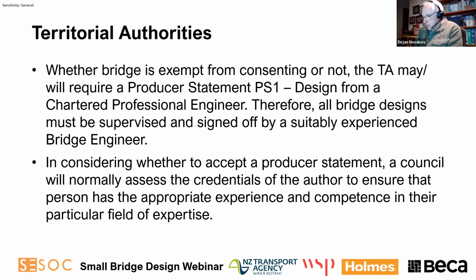Without repeating most of what was discussed previously, I might just add a few more things and refresh again here. First, to start with TAs and consenting requirements. Whether the bridge is exempt from consent or not, the territorial authorities may or will require a producer statement PS1 design from a chartered professional engineer.